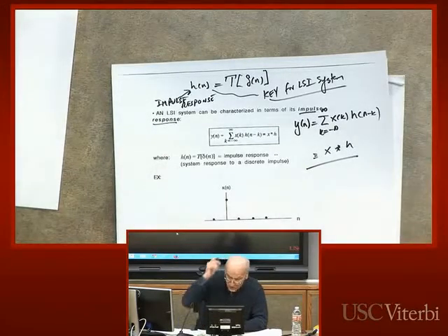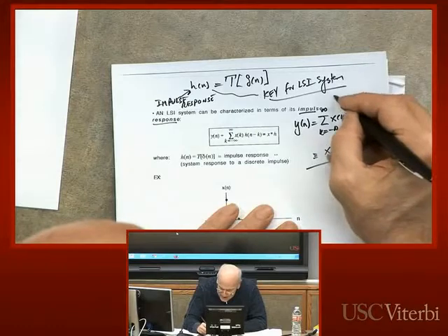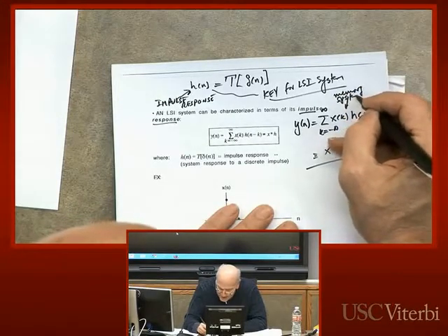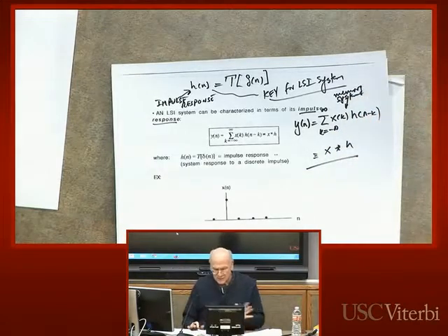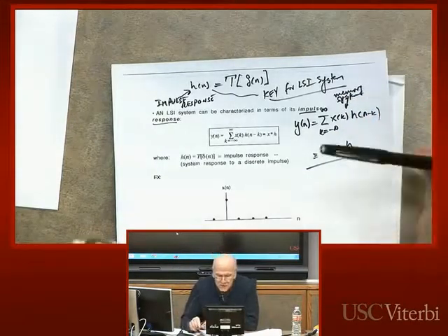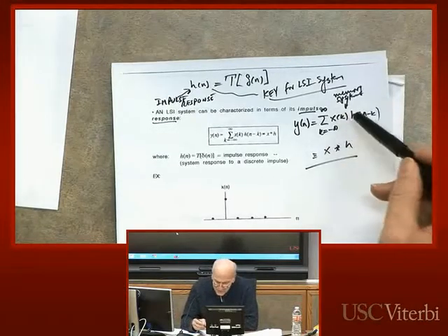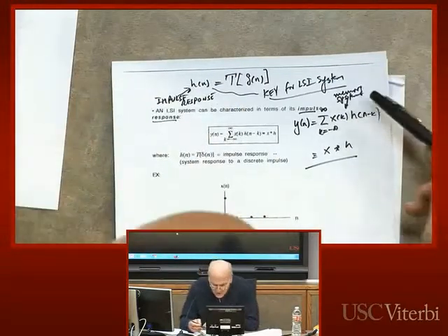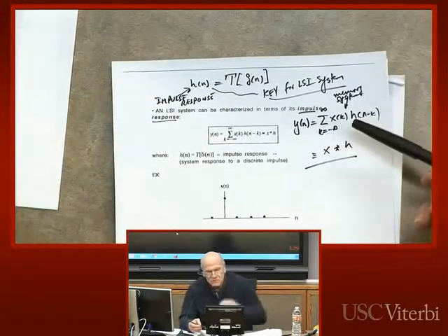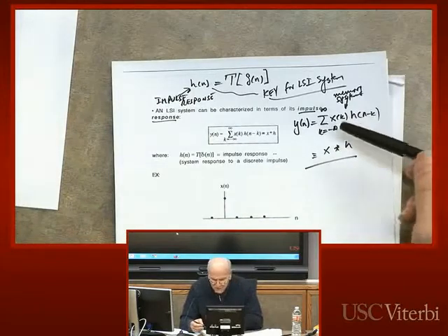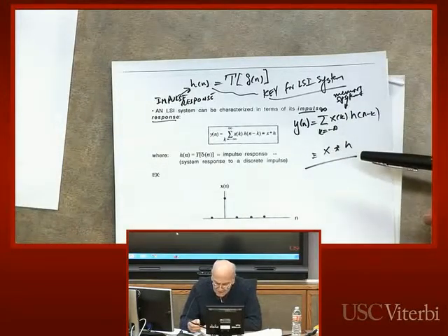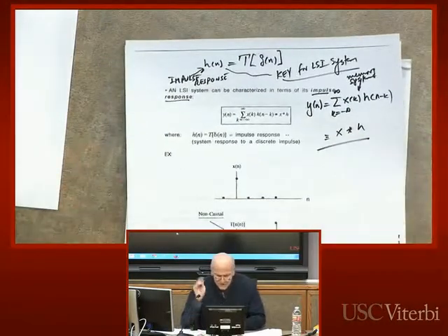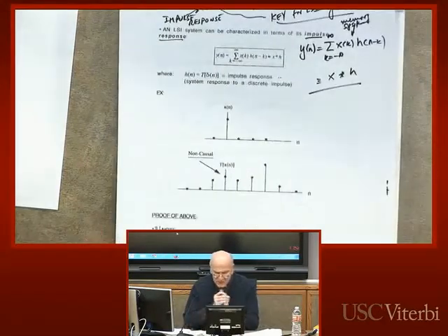One thing I want you to notice: this is not memoryless. This is a memory system. I didn't say anything about linear shift invariant systems requiring no memory. They do, in general an infinite amount of it, because you need samples of x from x of n all the way to plus or minus infinity. You need basically the entire set of samples. But once you have those in your memory, you've got y of n. So that's a very, very important concept for linear shift invariant systems.